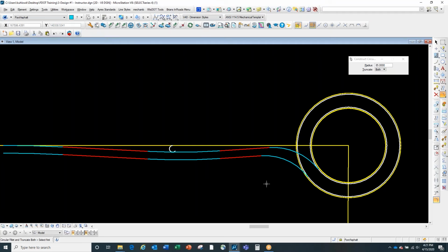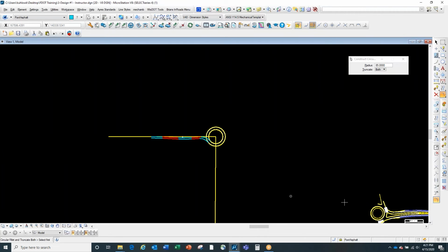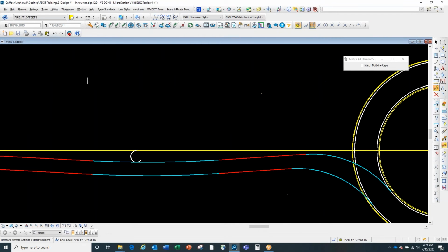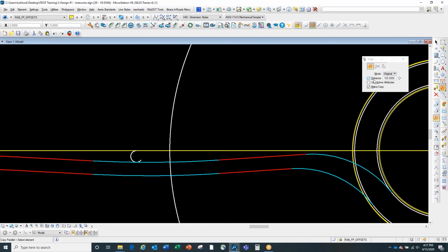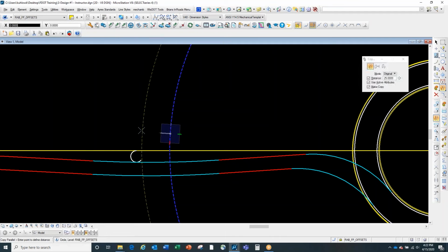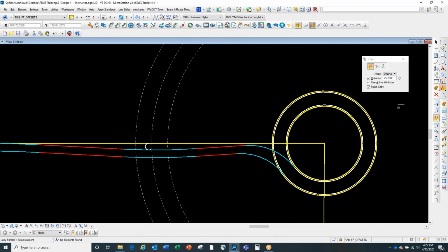Next thing through the process would be, what we learned previously, to go ahead and check the fastest path and then see if it accommodates the design vehicle. So let's do that fastest path check again real quick here. Just getting my levels all set up here. If you recall, we offset this 165. Make sure we're using the right level. There we go. And then we're going to offset another 25 twice.